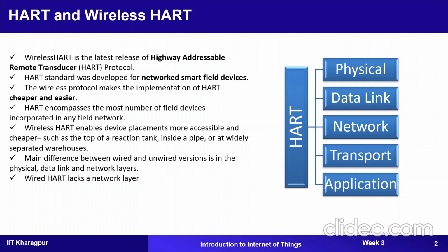The third layer is called the HART network and transport layer. It cooperatively handles various types of traffic, routing, session creation and security. Wireless HART relies on mesh networking. It means that each device is able to interact with every other device present in the network. Then each device is armed with an updated network graph.